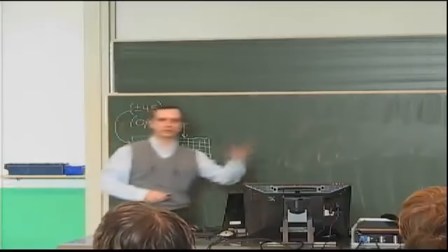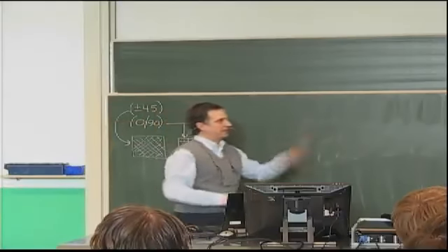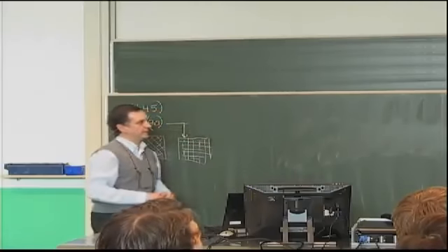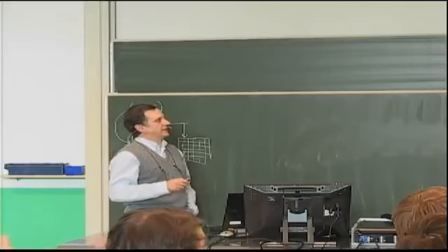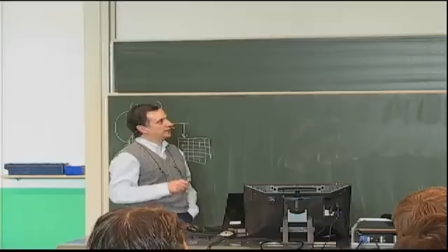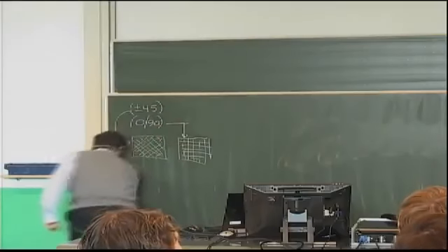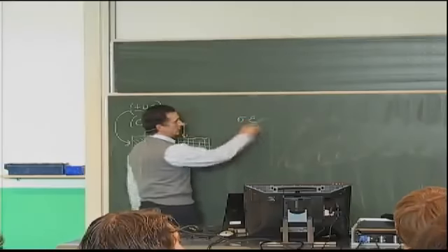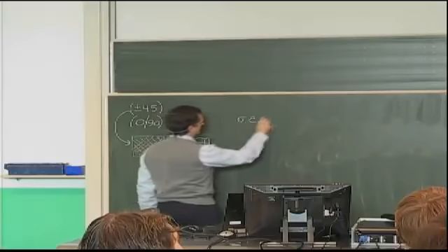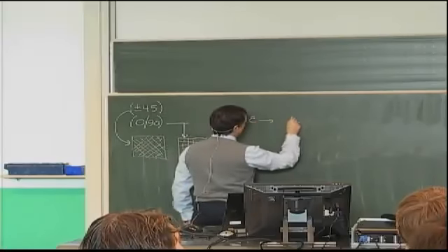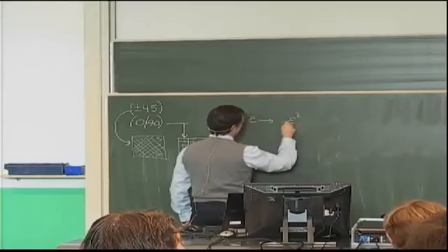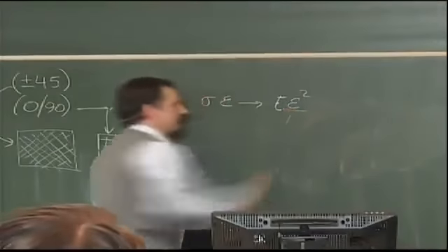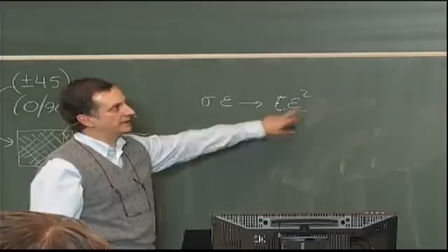The book has the whole complete derivation. This is the displacement-based energy for a laminate. You can take it for granted or follow the derivation. The main thing is what in an isotropic material would involve it's always a product of stress times strain that goes into the energy, and that, if you do it in terms of displacements, would be epsilon squared. You would have terms like Young's modulus times epsilon squared.